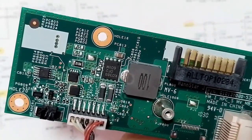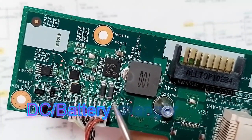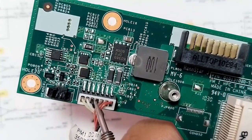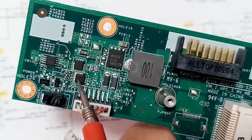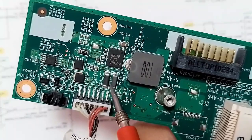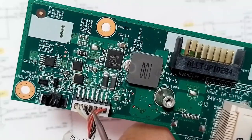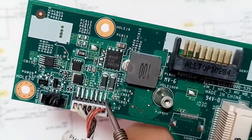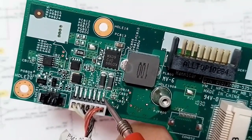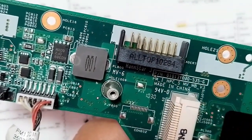So basically over here we have the charge circuit, or the DC battery charger, where we have, as you can see, the power jack cable. Okay, so as you can see here we have two power MOSFETs. As you can see over here we have two inductors. Basically these two inductors are connected directly to 19 volts. Here we have this red cable means 19 volt. So two inductors, we should basically find here 19 volt. Okay, we have here another MOSFET, we have an inductor, and over here we have the battery connector.